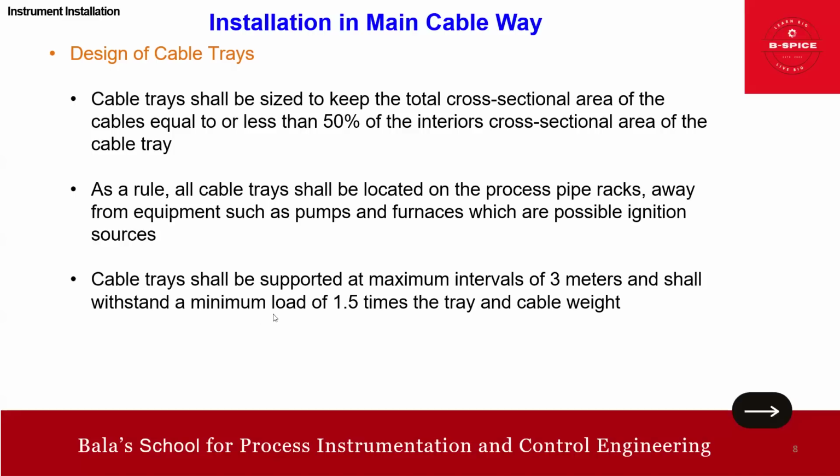Then cable tray shall be supported at a maximum interval of 3 meters. Every 3 meters you should have a support actually. And it should withstand a minimum load capacity of 1.5 times the cable tray and the cable weight. So you should calculate this, okay? And of course, we have to specify this to the vendor.